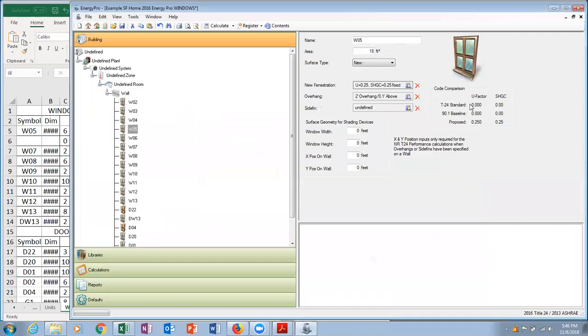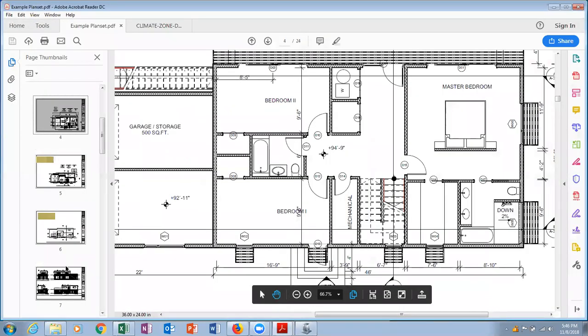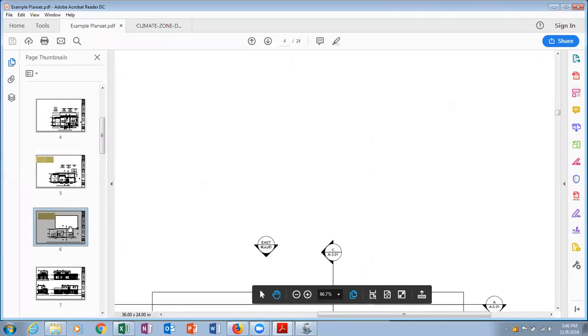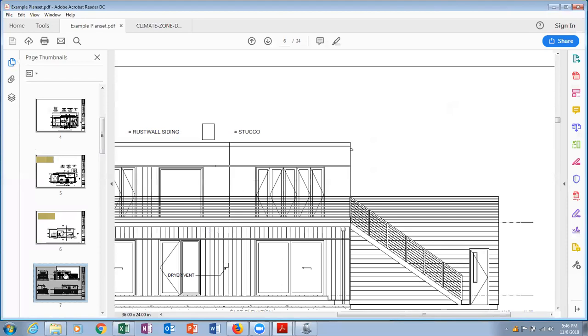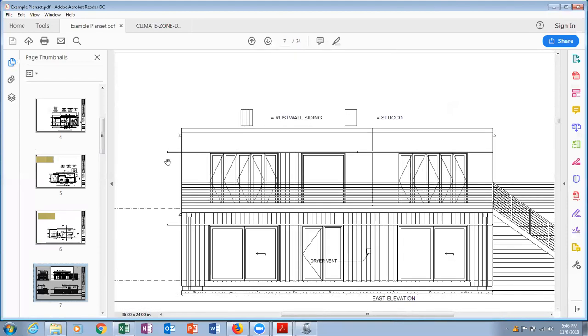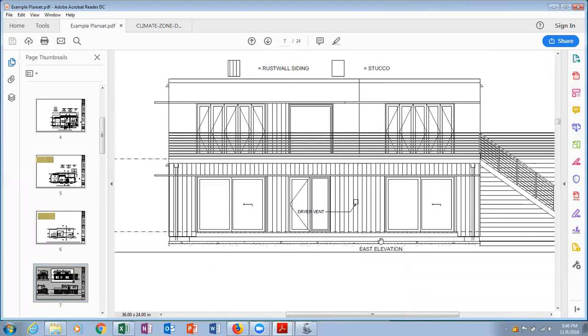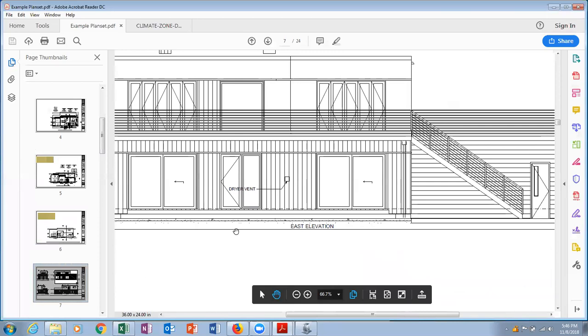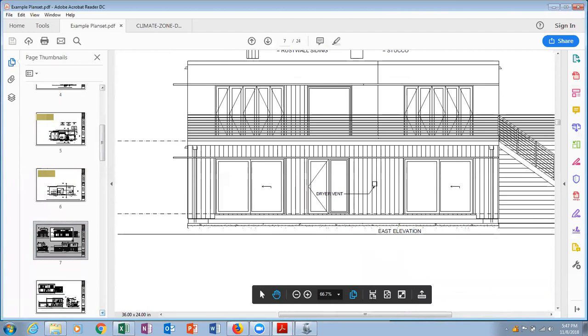And select OK. And then after going through the building plans, I noticed that it does have an overhang. So I went ahead and added a 2-foot overhang to everything. And I found that on the building sections where you see this little line that comes out on all the different sides of the building. And when I zoomed in with my ruler at a 1/4 inch for every 1 foot, it came out to be a 24-inch overhang or 2-foot overhang.